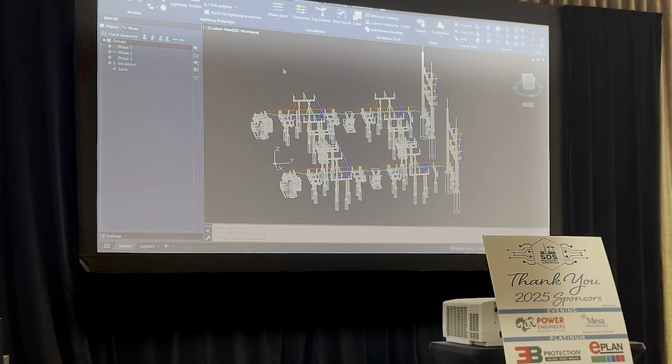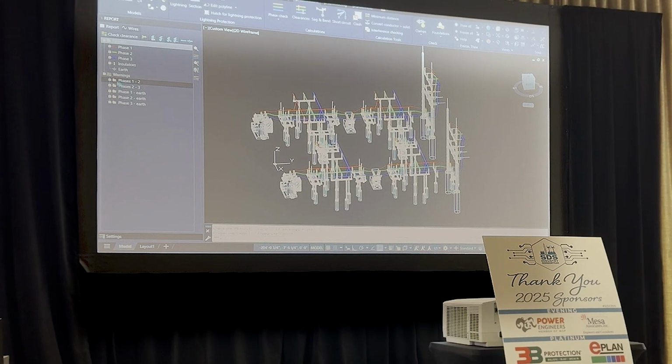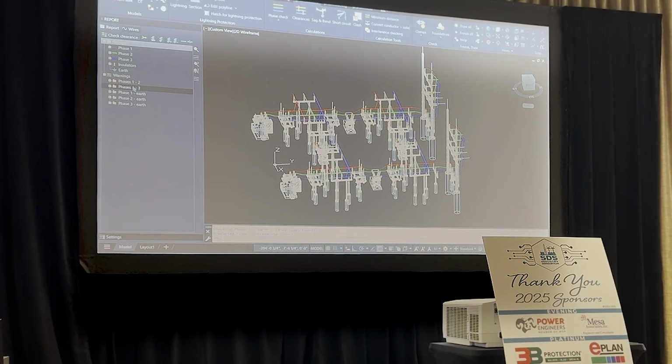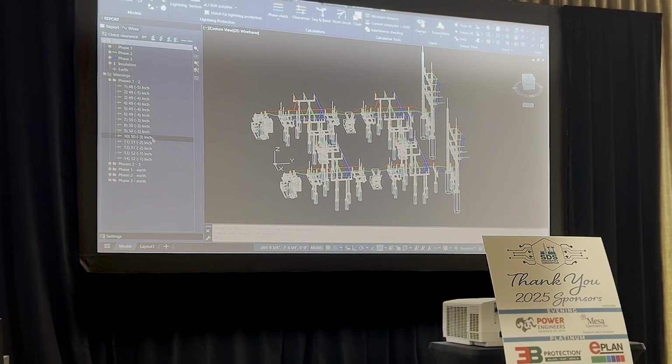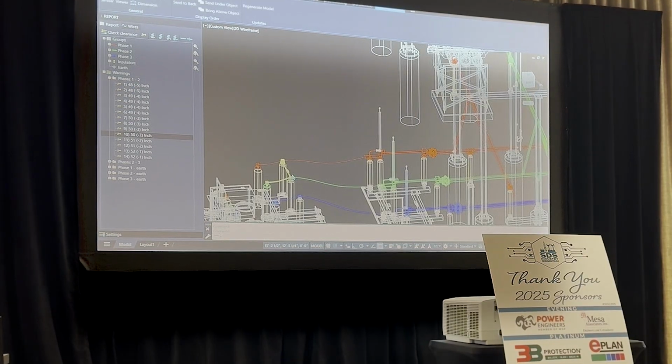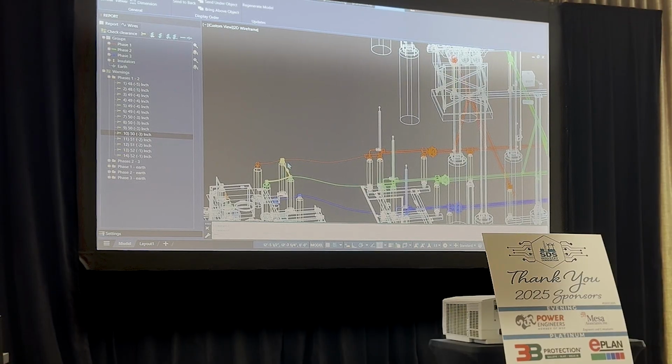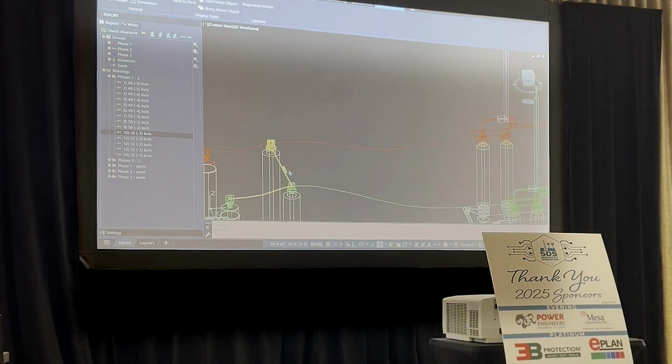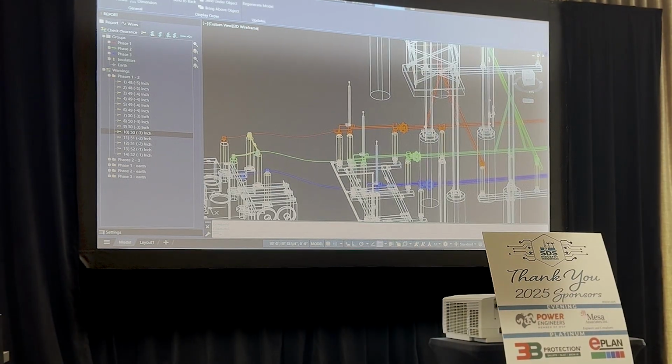So I went ahead and entered those. And you'll see something pop up here in a second. So you see all these warnings. This is saying between phases 1 and 2, I have issues. And you can look at what they are. Like this one, for example, is over here at the transformer because I'm using a clearance that's outside of this voltage tray. So it's telling me that these two things are in clearance with each other.